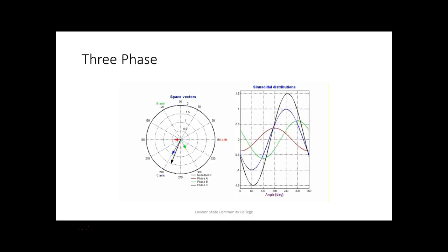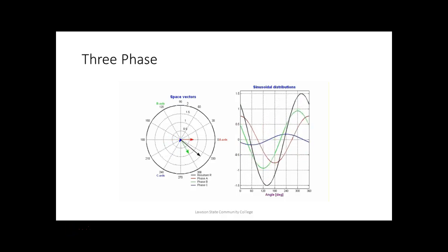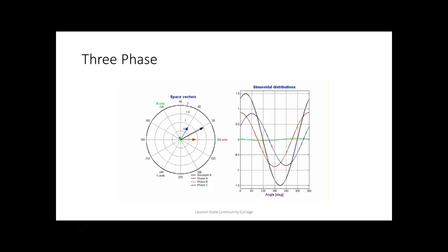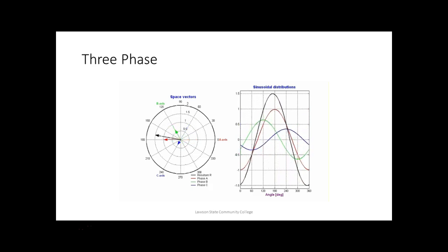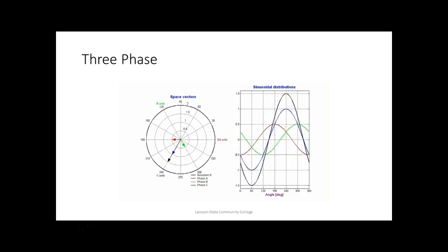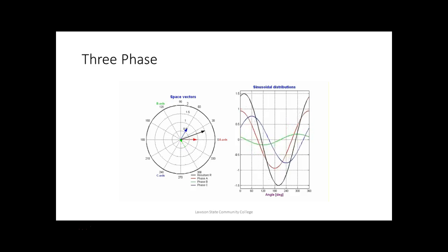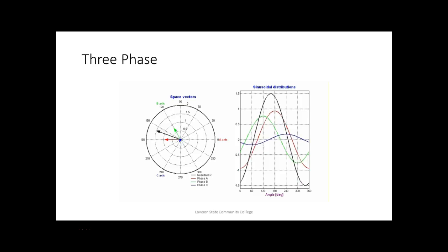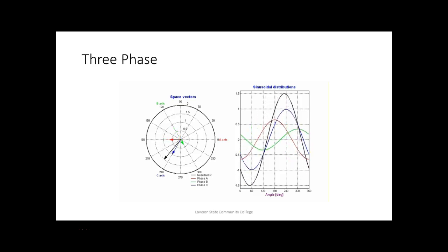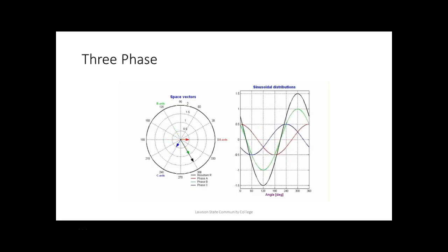This is just looking at it at a time. So green phase, blue phase, yellow phase, and this black right here is power being created by the two. So you can see as it moves, the power automatically moves around the outside. So what we do with a 3-phase motor, we automatically create a rotating magnetic field in the stator.